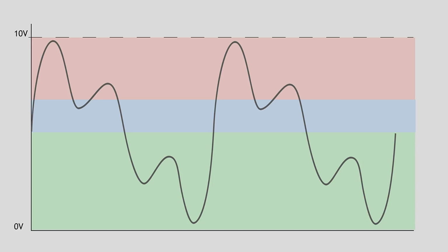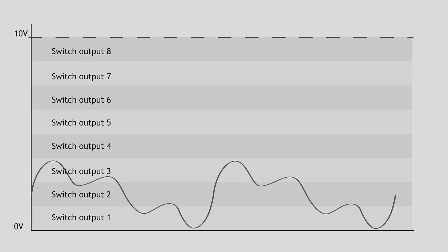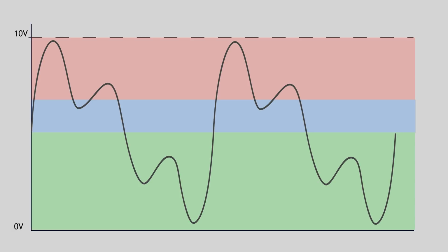You could achieve something similar with a usual switch module with CV output addressing, something like this. Or if you attenuate the main voltage source, you could achieve something like this. In that case, you will get equally spaced boundary points. But I want to be able to set boundary points at specific voltages. In this tutorial, I want to show an implementation of this idea using comparators.